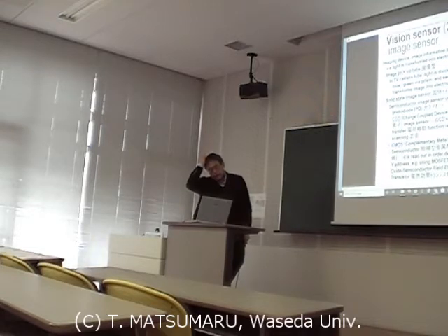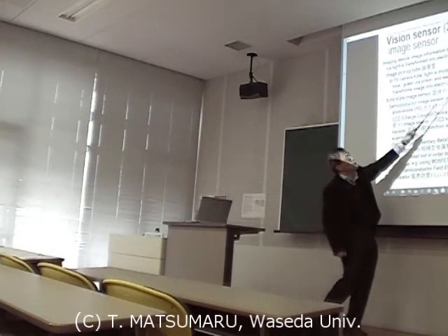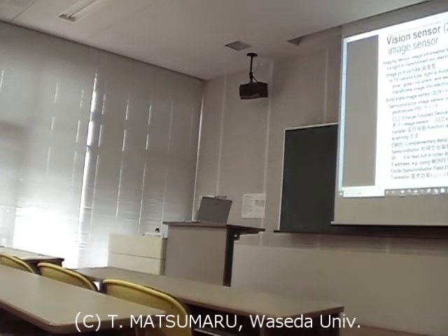Make it two-dimensional, and the image sensor is like this. There is the image pickup tube, and for the color image sensor three lights are used, but mainly whether one light is detected or not. The solid state image sensor, a semiconductor image sensor using photodiodes, is divided into two types, CCD type and CMOS type.